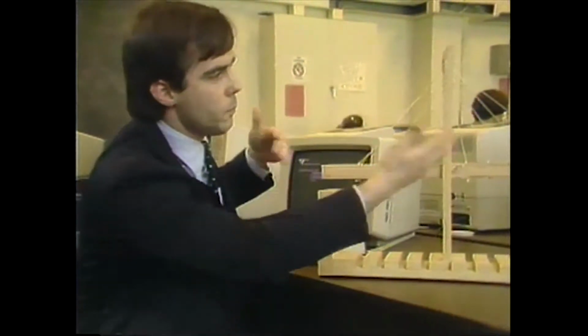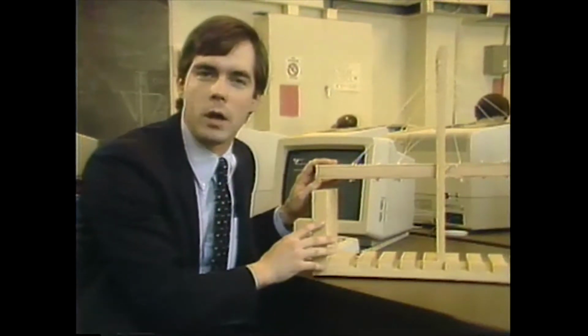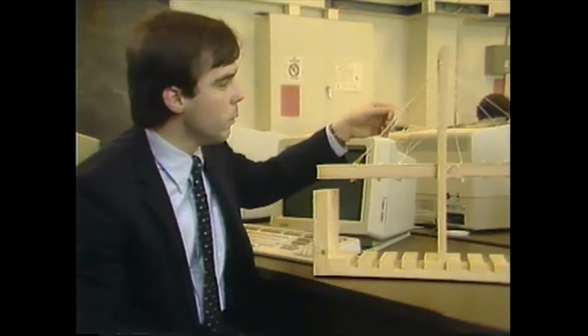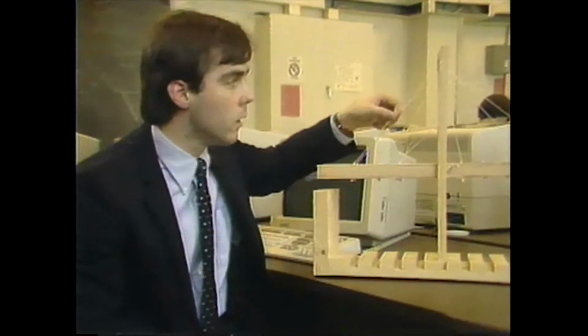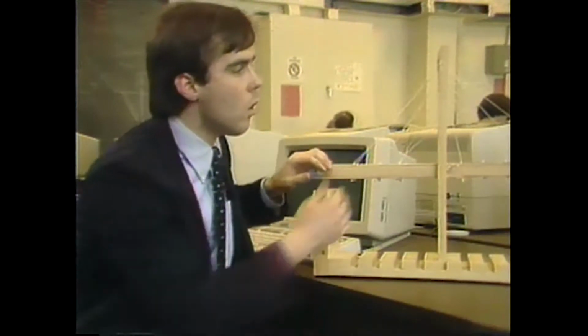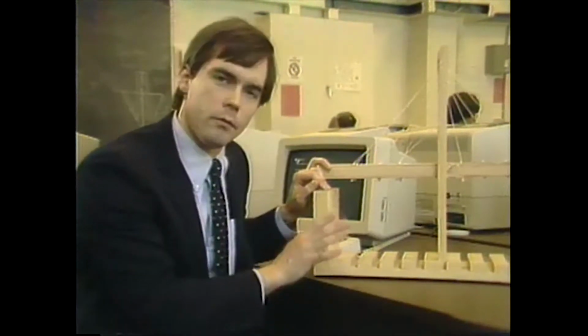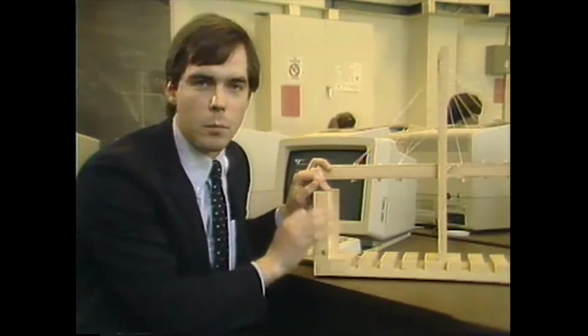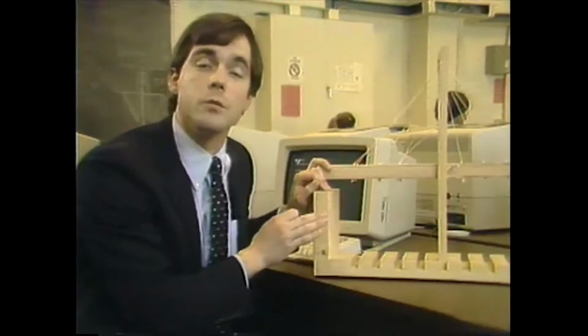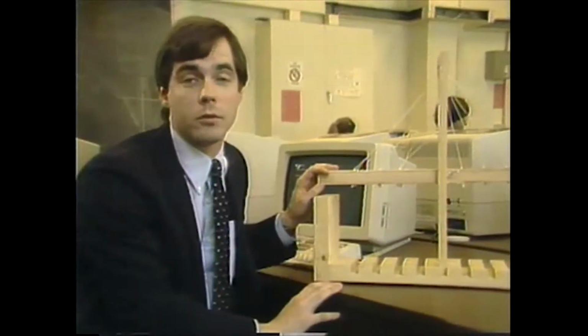The third program that I want to show you, Growl Tiger, is the Structural Analysis and Model Building and Design program. In this case, the students, having decided on a general structural configuration, perhaps the thing from which they eventually built the model, what they'd like to do is to be able to run through an analysis and find out how big the forces are going to be in the strings, or how much the beam is going to move. Growl Tiger allows them to build very rapidly a mathematical model which gives reasonably good predictions for the behavior of the actual structure.